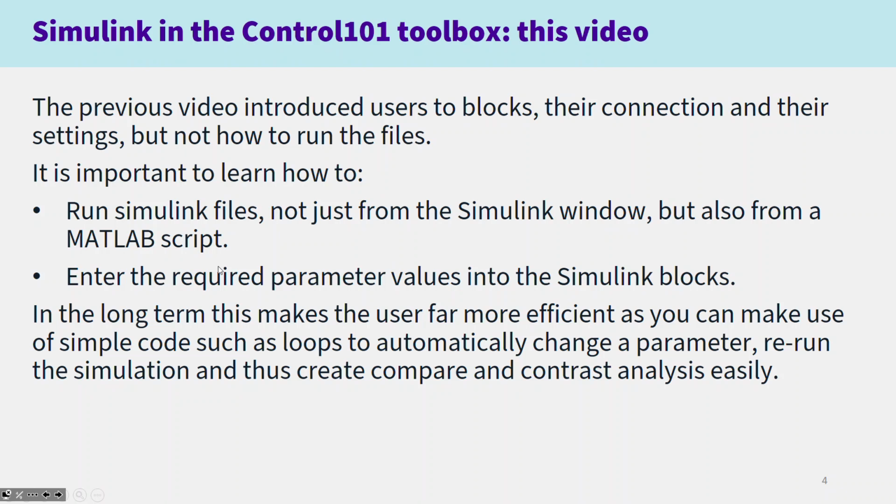In the long term, it's a lot easier to do this from a script because it's more efficient, because you can use loops to do things like change a parameter systematically and overlay the plots that you get from the simulations with these different parameters and so forth. So I'm very much a believer: run your Simulink files from a MATLAB script. It makes your life easier and more efficient in the long term.